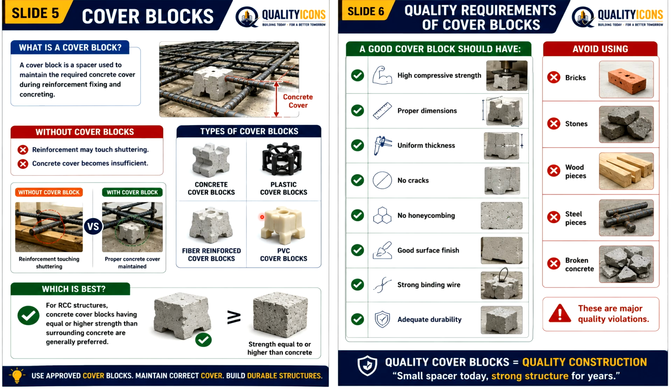When concrete is poured, steel directly touches the shuttering. The slab loses proper cover. That is why QAQC engineers must always conduct a final inspection immediately before concreting. Without cover blocks, reinforcement may touch shuttering. Concrete cover becomes insufficient.